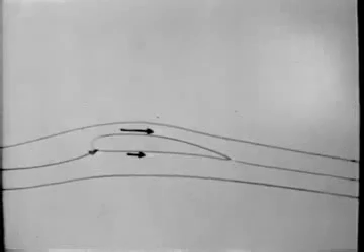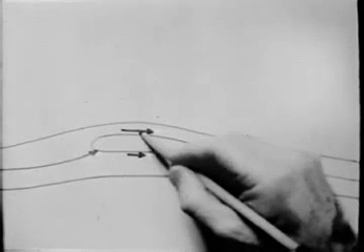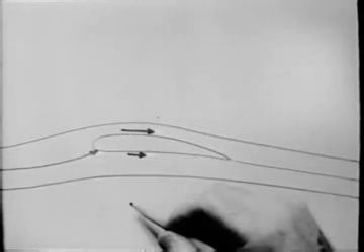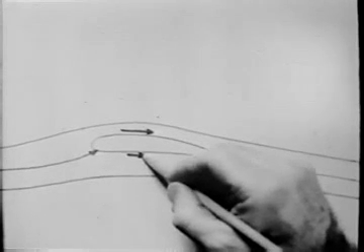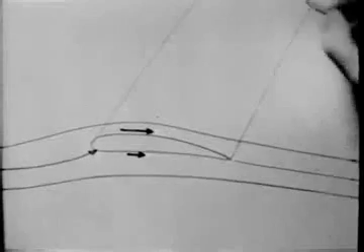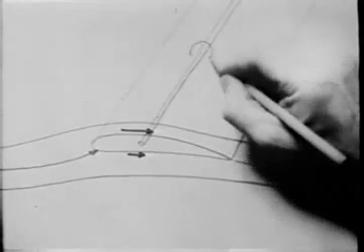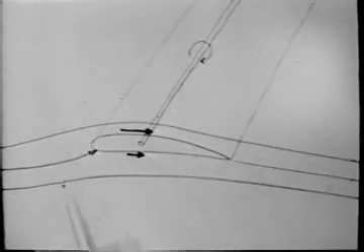A wing generates lift because of the higher pressure below and the lower pressure above. According to Bernoulli's theorem, the velocity on the upper surface must be greater than the velocity on the lower surface. This means that there is a net circulation around a lifting wing. Often we pretend that this circulation is produced by a vortex, which is bound in the wing, and which accounts for the circulatory movement. We don't care whether the vortex is really there. We care only about the circulatory velocity field that it creates.